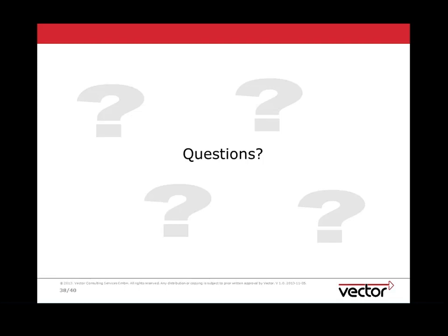Another question was if the ISO 26262 is now supported in AUTOSAR, and yeah, if you have a look at the Vector site, you can see that we provide you with some help in implementing ISO 26262 using AUTOSAR with the MicroSAR Safe solution, where we have an operating system that is certified up to ASIL D, and of course the end-to-end protection library of AUTOSAR 4 helps you implement safety mechanisms.